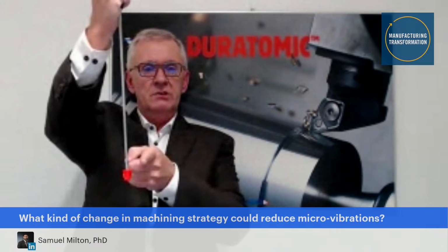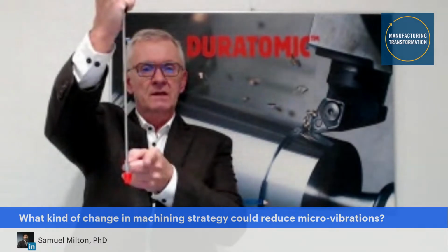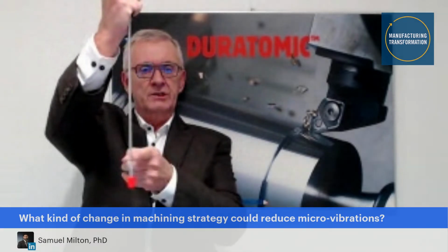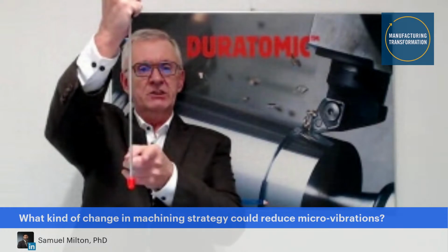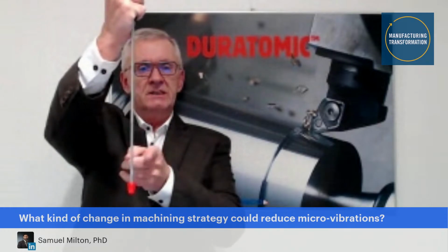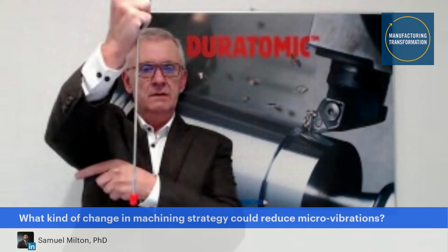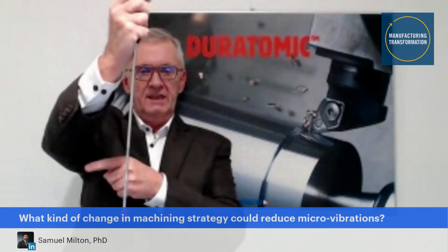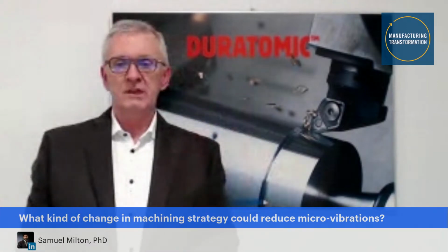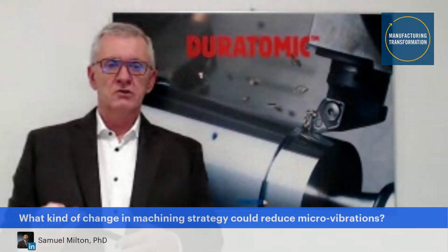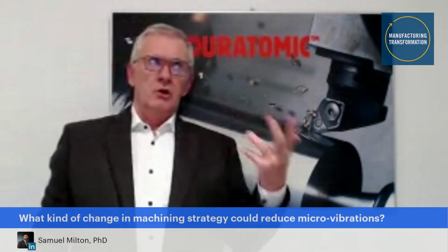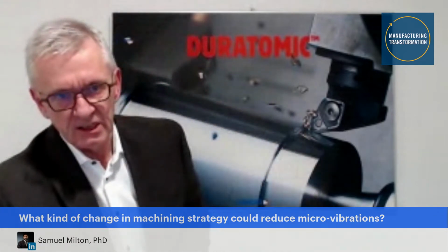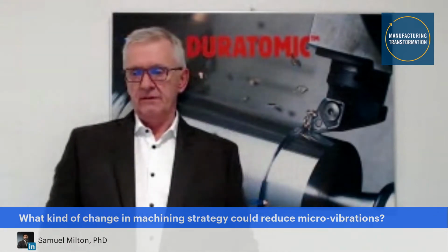It's only when you start to do this, modified cutting forces, variations in cutting forces, this thing starts to vibrate. And you don't need to bend so much for that. It's the variation that makes the difference. Not the size, not necessarily only the size, the average cutting force.